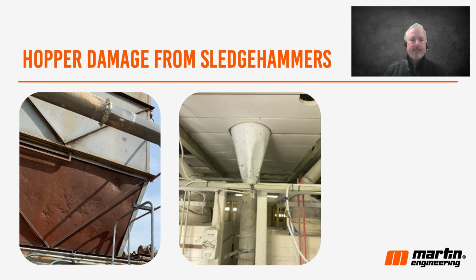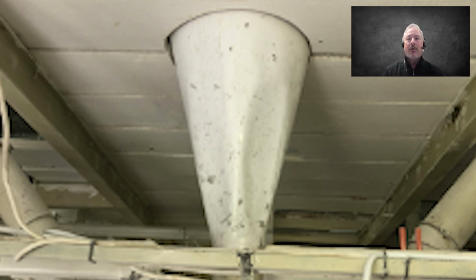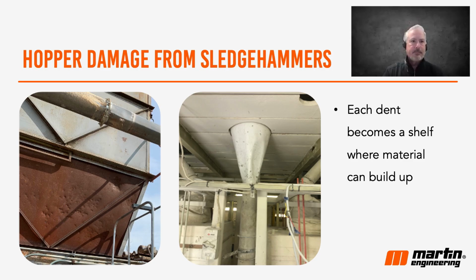And here's a couple photos of what can happen to the structure when using a sledgehammer. You can see in the cone photo in the top right, they've caved that whole cone in from beating on it with a hammer. And then on the lower left, you see all of those dimples that are created in the side of that wall where they've been hitting it. Each one of those dents on the inside of that hopper creates a shelf for material to build up upon. So it really just enhances the issues that they're experiencing.